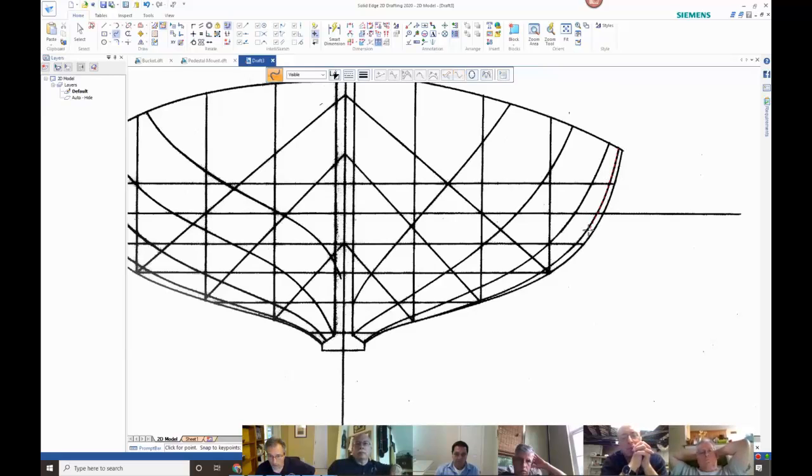I just used this curve tool. Now, I stay away from using this curve tool to actually fare through points, because it's not like a spline, and you can easily make it serpentine, which would be no good.